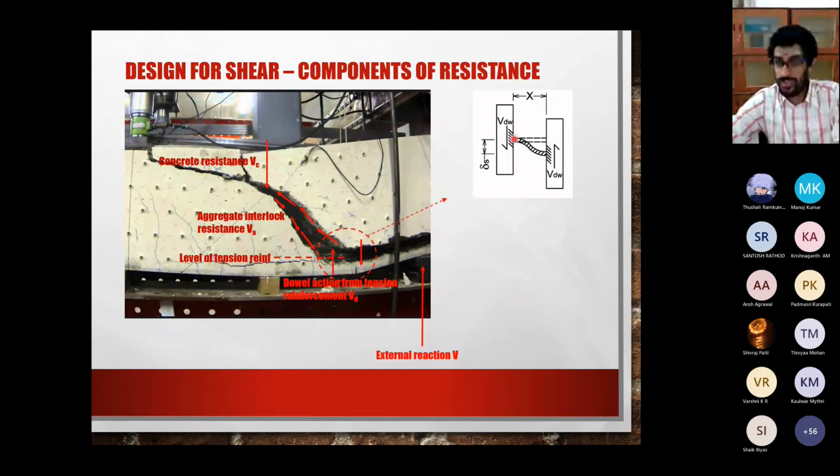So basically, if you have a bar and only shear is going to cause your shear cracking. So if you have a shear across a reinforcement bar which was originally like this, a straight reinforcement bar, and there's shear trying to shear your steel, that is not that easy. So this bridging action by the steel is known as dowel action.